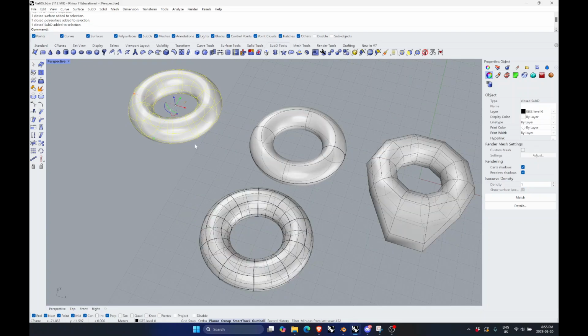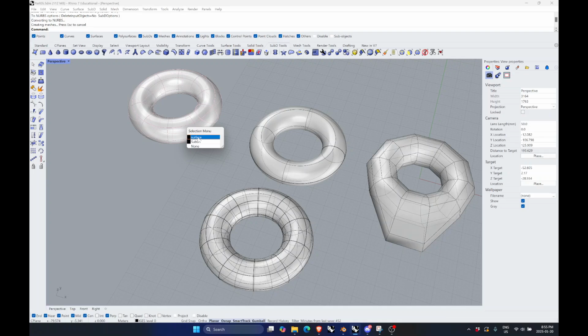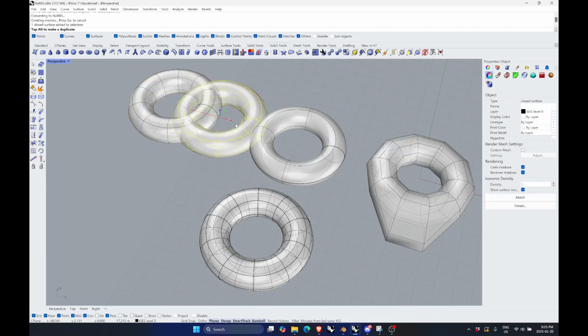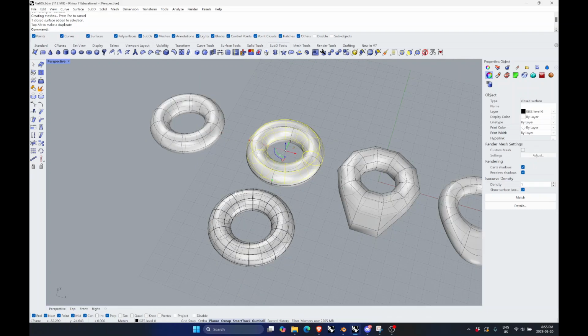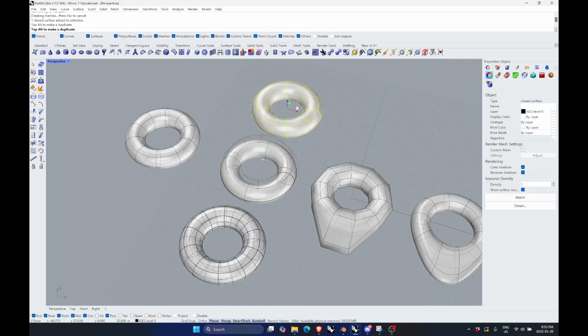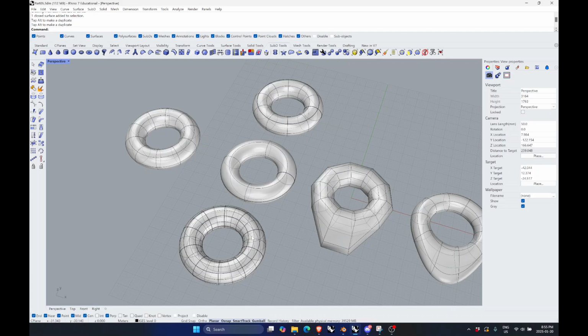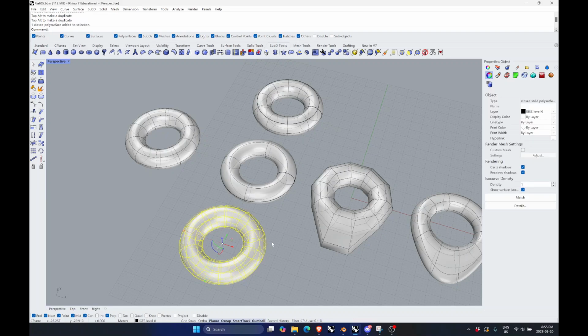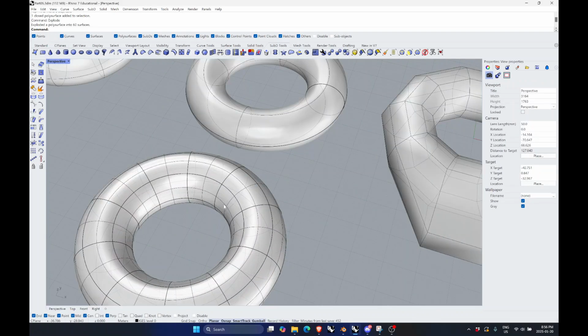Let's see if we were to go back to sub-D and go to NURBS, sub-D options, faces unpacked, or faces packed, I guess, this time. Right click, and now it's given us a geometry surface. Now you can see it's a surface when I selected faces packed, which is interesting. So faces unpacked gives us a closed poly surface, and if I explode this, it gives us 60 surfaces.